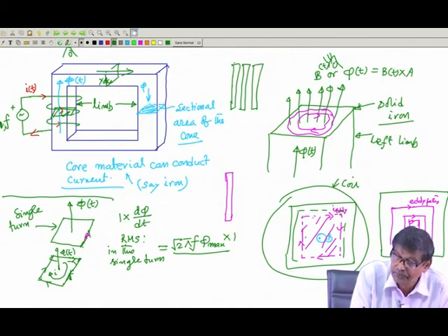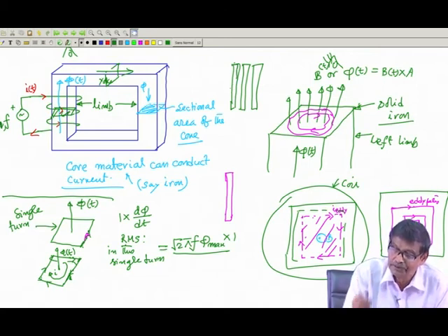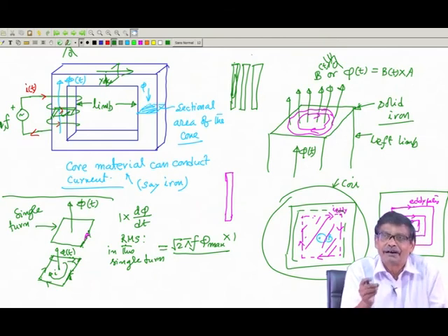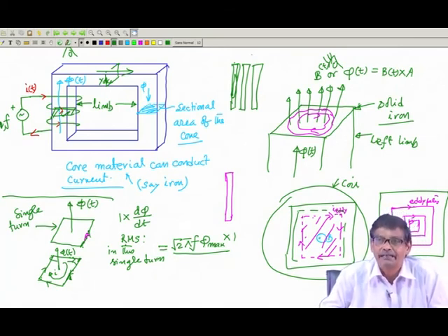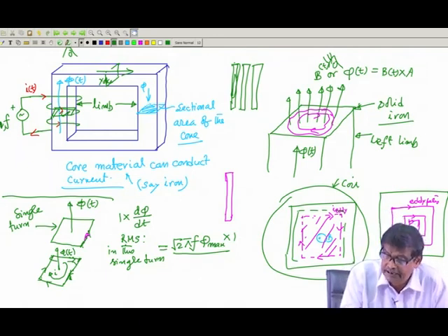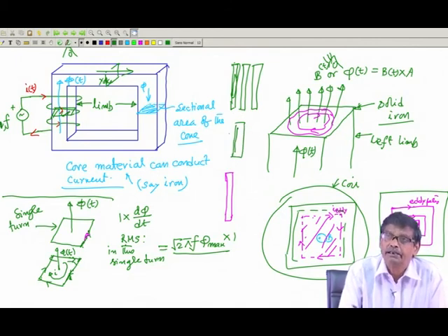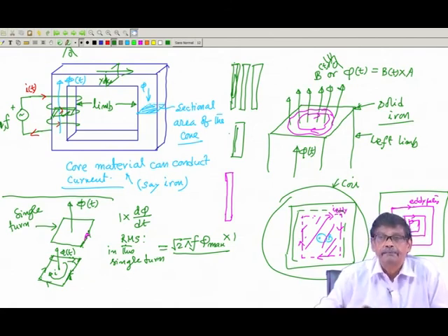So, this is a plate and there is phi perpendicular to this, there will be eddy currents now, but if you make thinner plates, the eddy current paths, or the number of paths available, will become less for each of the plates, given that each plate is electrically insulated from the other. So, if you concentrate on a single plate, you will see that in this plate the eddy current loss will be less.